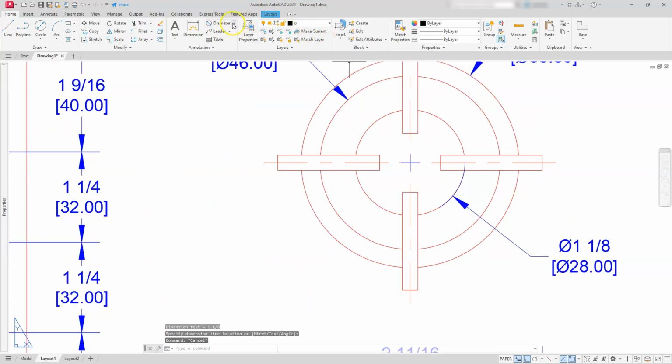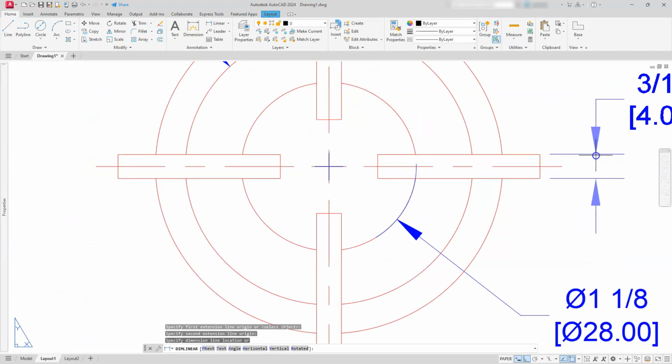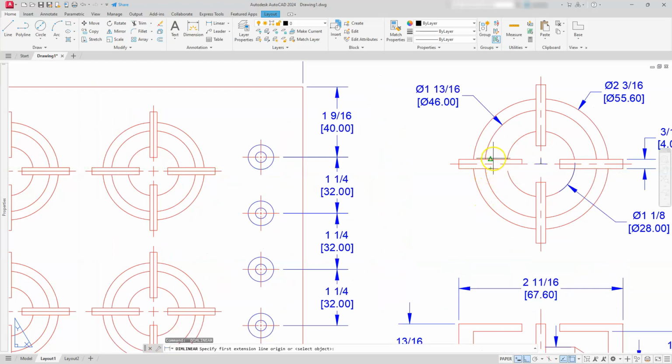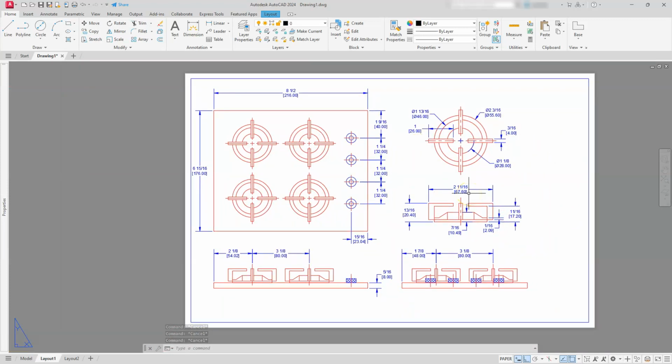Let's go ahead and put the linear dimension back on here just to show you the thickness that's located from here to here. And then I'm going to give you a reference dimension here. Let's tell it that it's this tall. Sometimes you'll have some dimensions that cross over into your object. It's easier sometimes just to select it and kick it to the outside, right? Okay, so that's kind of all the dimensions that I'm going to need just to adjust this one.